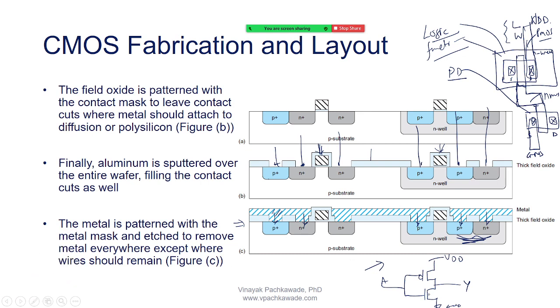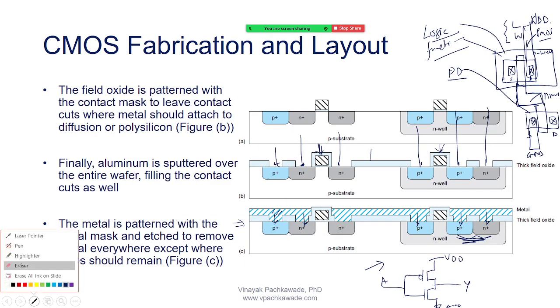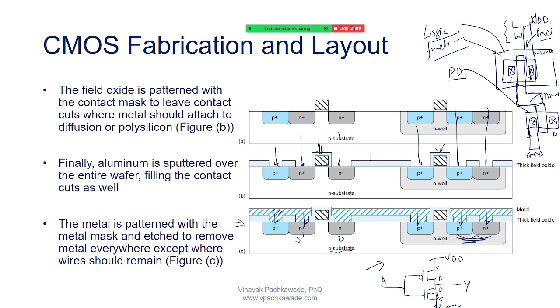I know that the body of the NMOS, I show through the symbol like this. This is source, this is drain, this is source, and this is drain. So I know the body of an NMOS is tied to its source. So where is the P substrate? Here, source, drain of the NMOS, and that is tied to P.